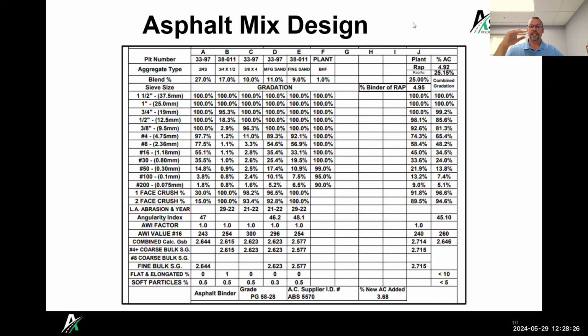And that's another thing that, by specification, your blend has to be able to meet as well. So both of those things go into what types of aggregates you're choosing for your mix design. So in order to meet those specifications, you have to use certain aggregates. Both of those results and values are good for 5 years. They usually check those every 5 years.